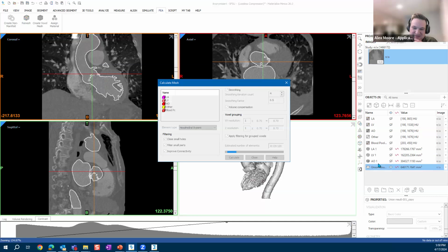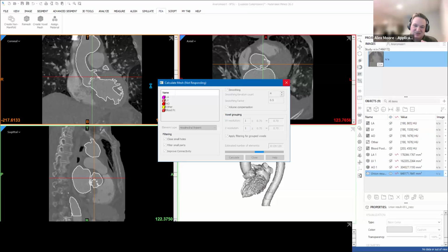This is just going to use my segmentation, and once I have a voxel mesh, it's going to be the same as a volume mesh. I don't like to do it this way. I like the control that you have in 3-matic. But I can create one here, and then I should be able to walk you through the material assignment of how we go about doing that.